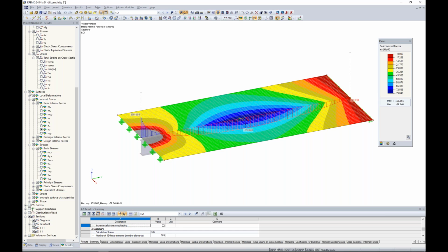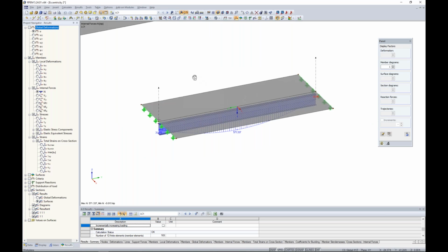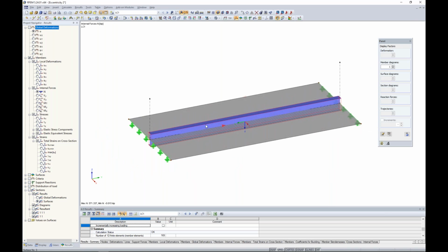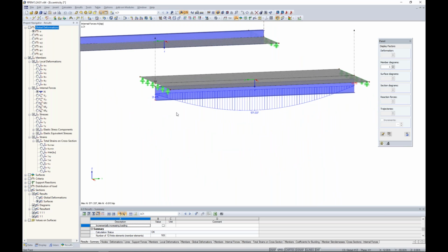In turn, if we turn off our surfaces, let's take a look at our members. And we're most interested in, and let me cancel my visibility and turn off my sections, the axial force of the member. Looking at my system up here, I don't have a single axial load within this member at all. So it's not taking any of the tension. Well, here we have a very high tension force, 571 kips. So that's exactly the behavior we'd expect.